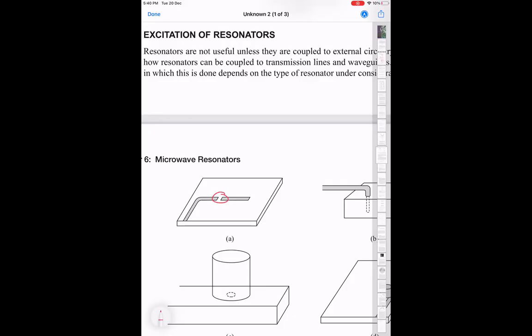Right? So this is the coaxial connector, which basically you can just think of as a coax. And then on the inside, there is a small hole. I will pass this around, you can see. The pin is not visible because the pin has been chosen to have a certain length that it's not even entering the cavity. But because there is a hole, there is some field line coupling to it. That is just because of the choice of how much coupling to the external mode we want. That's how you tune it.